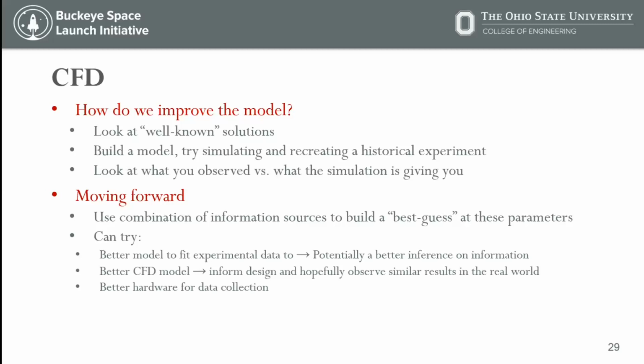We talked about why our acceleration data on the TeleMetrum was super noisy. It was suggested to me that there is structural noise. So the accelerometer might have been picking up a vibration in however it was mounted inside the rocket, and that was showing up in our flight data. So you could look at the design of that, make that more rigid in the body or less rigid, depending on what's going on, actually.